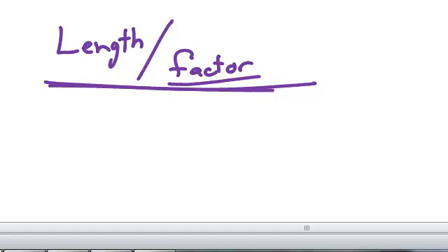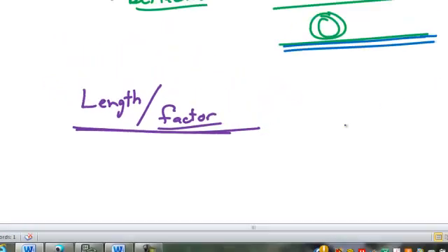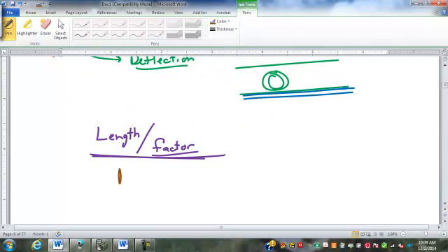Page 403. So you can see for different applications, roof beams. Typically, your roof beams are allowed to have a little bit more sag to them, a little bit more deflection. I mean, you can see you got L over 180 standard for live loads, L over 120 for your dead load. So you're saying the dead load can sag more because